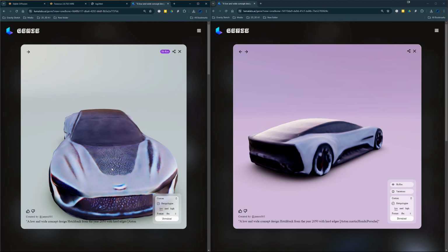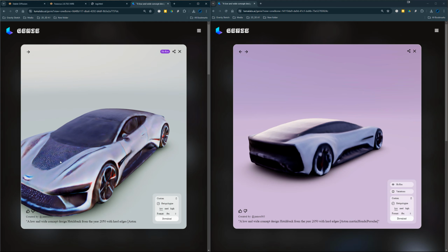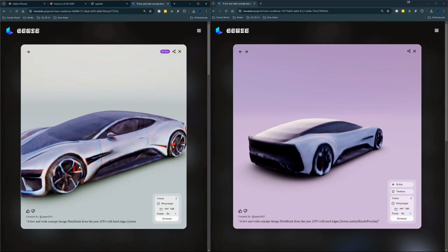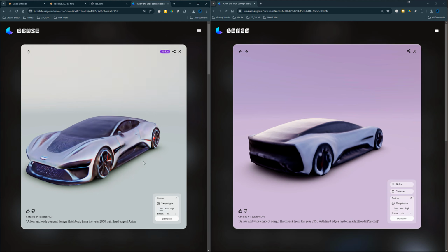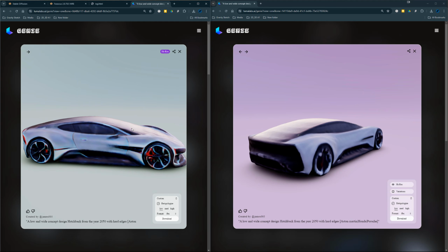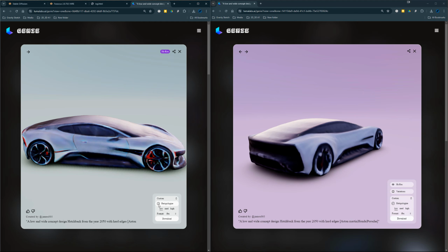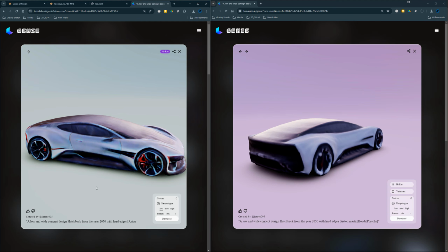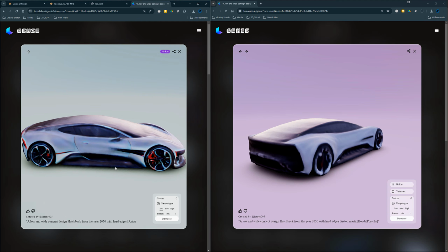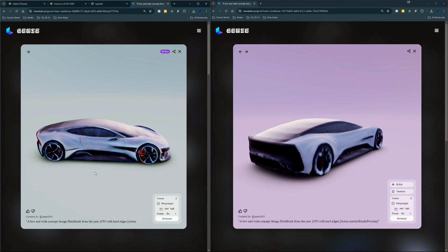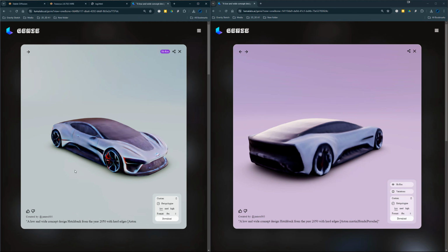Sometimes this noise, I've noticed, will cause an issue when running it through image to image, but I think I'm going to give this a try. So we'll use this model in the next step in Stable Projectorz. So the next thing I'll do is come down to retopologize. I'll keep it on low and I will export an FBX model. Some things to note: Stable Projectorz right now at the moment only supports Y-up coordinate space, and I know from experience that this will export as a Y-up coordinate space, so we can use it directly in Stable Projectorz without having to reorient it.